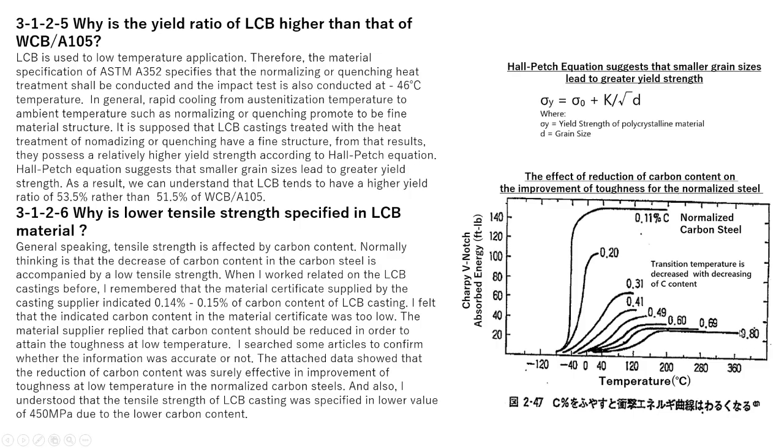The carbon content indicated is 0.8%, 0.69, and so on, gradually decreasing. The profile indicates that absorbed energy increases with reduced carbon content. So toughness increases with a decrease of the carbon content.